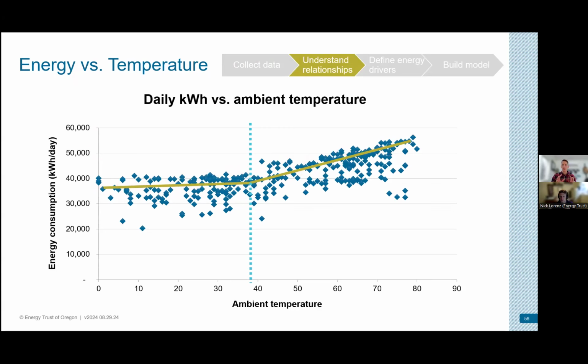And this kind of understanding really only happens when you chart the data and explore the data to look at different types of fit and to see what results in a model with the best fit and the lowest error. And that's the kind of stuff that the SEM engineers are going to be doing when you provide them with your energy driver and your actual energy use data. They'll be charting all of this to see what is the proper relationship for your facility between outside air temperature and energy use, and different production metrics and energy use, and different operating schedule variables and energy use.